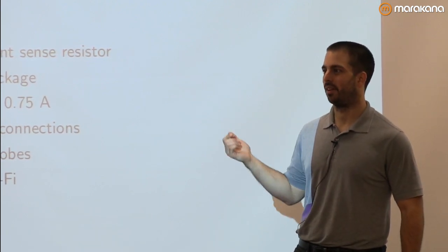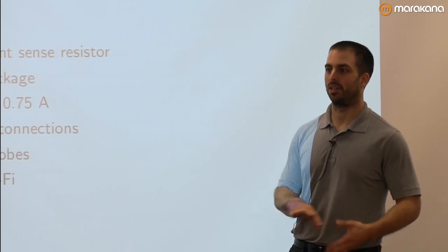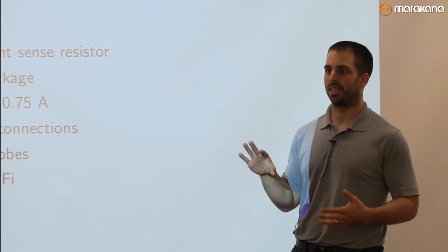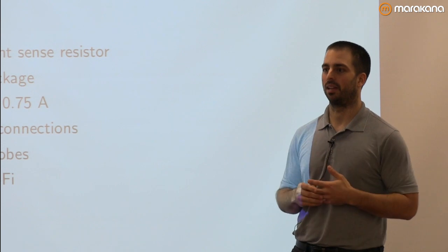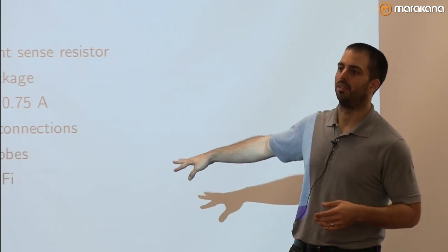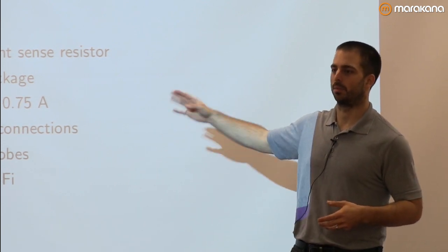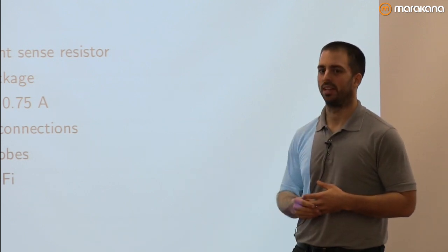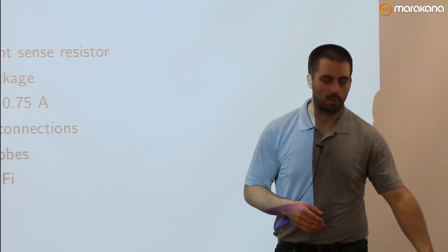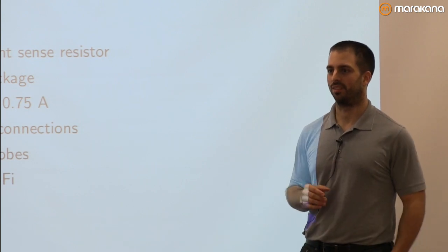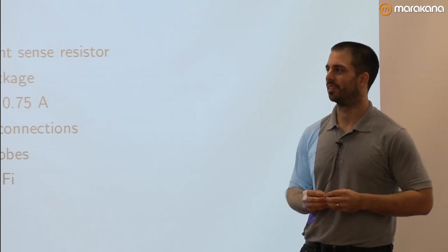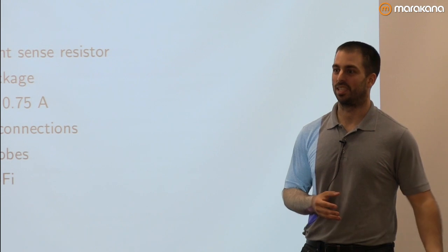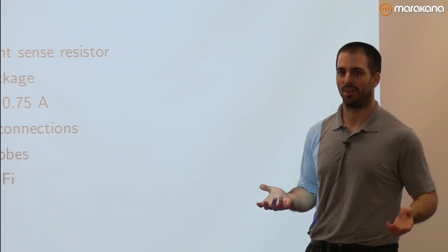I found ADB over Wi-Fi pretty useful because then you can load the program that you're going to test, and you can get some debugging info. But then you need to turn Wi-Fi off, unless you're going to subtract it out of your measurements, which you can do as well. So that's another handy tip. Because if you leave it plugged into USB, your measurements will be wrong. You might even get 0. I've gotten 0 before. I was like, 0? What the hell?